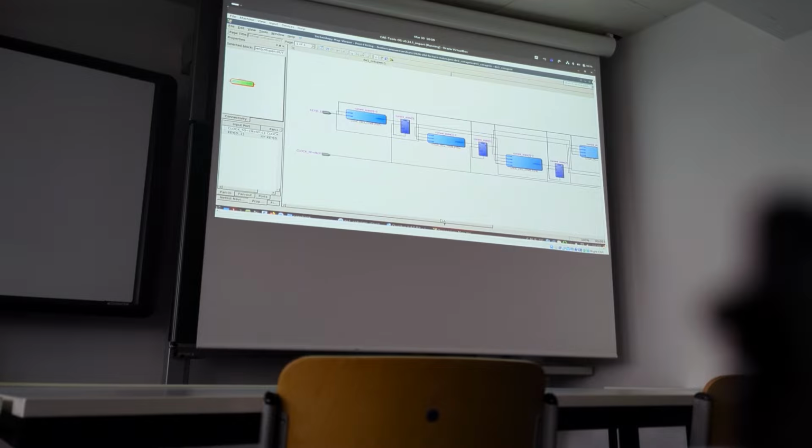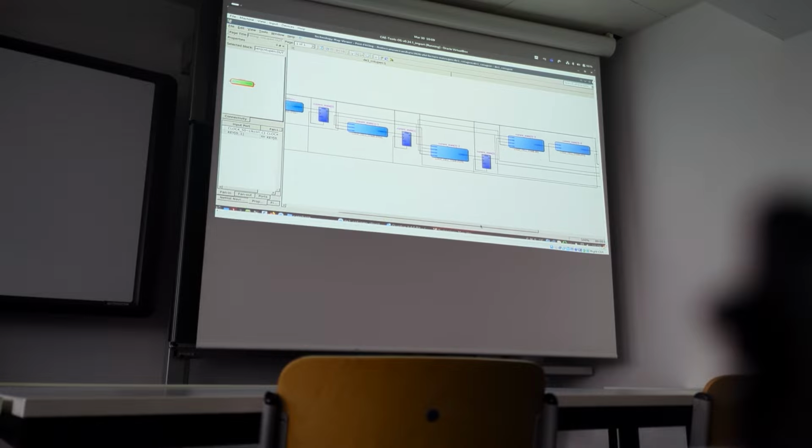Then we see an example which is nearer the technology of the FPGA. And you can see for a 4-bit counter, instead of this state register where the 4 flip-flops are stacked, here we can see the individual flip-flops. Current state 3, 2, 1, and there should be 0.